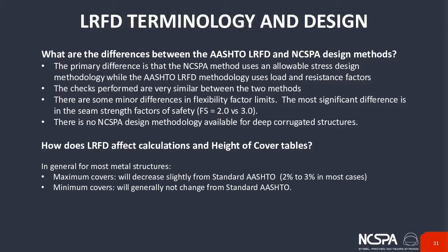The AASHTO LRFD methodology, LRFD stands for load resistance factor design. So it uses load and resistance factors to essentially get to the same end goal, which is to make sure that there is a sufficient amount of excess capacity within the structure to safely handle the service loads that it's going to be seeing. So one uses a load and resistance factor methodology for determining what the performance limits would be. The other applies an allowable stress factor of safety approach.